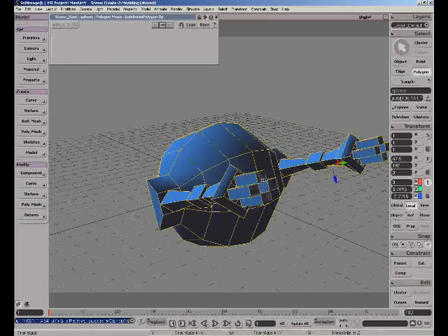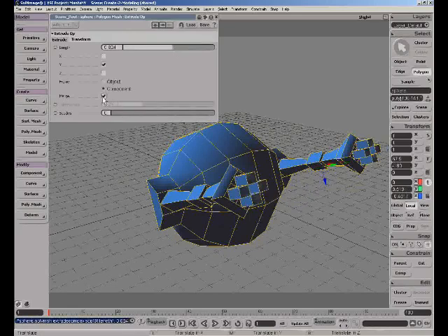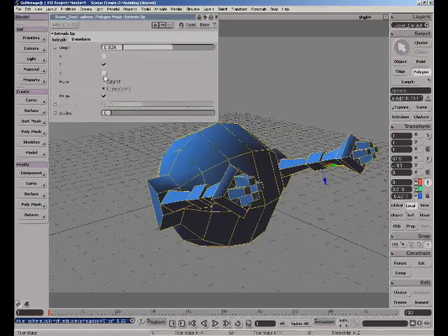Now notice when I duplicate them, I don't really get a lot of control. I just duplicate them and extrude them out. I'm going to go ahead and undo that and show you another little command. We'll right click on here and extrude along axis. Well, this basically gives me the same ability. I can extrude those polygons out, but I have this little check mark here called merge. I'm going to go into my transform panel and just decrease the scaling a bit. And now if I go back here, click on the merge button, you can see that'll merge and unmerge those polygons. So this is really nice.